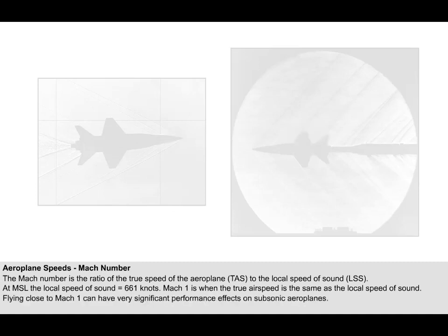As the airplane's speed approaches Mach 1, the compressibility and approaching shockwave can have very detrimental effects on the airplane's performance if the airplane is not designed to mitigate such effects. As a result, most commercial airplanes in service today have a limit on the maximum Mach number they are allowed to fly at. This maximum operating Mach number is called MMO.